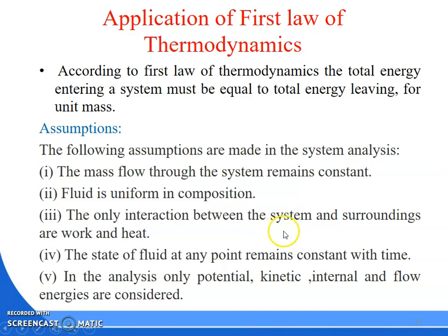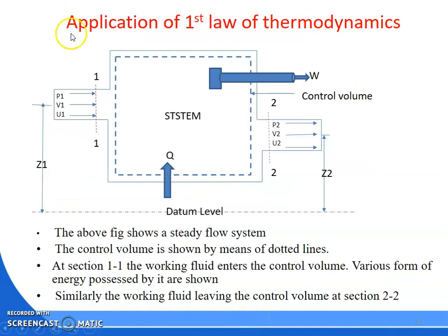The only interactions between the system and surroundings are heat and work. Only the heat form of energy and the work form of energy will interact between the system and surroundings. The state of fluid at any point remains constant with time. That means it is steady state condition, steady flow energy equation, or steady state fluid. In the analysis, only potential, kinetic, internal and flow energy are considered. If flow energy is considered, it is also an open system. These are the assumptions that you have to remember.